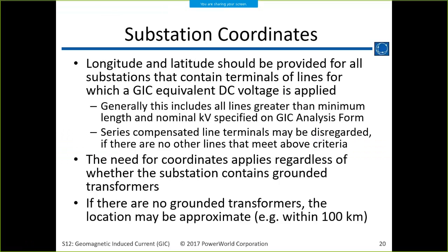So from your experience, on the lower kV 115, 161 kV systems, the lines are much shorter compared to the longer transmission lines, the transformers are scattered everywhere, and there's a lot of impedance on the system. For the same 5 volts or 10 volts per mile kind of default number, will including all that information actually change the results? Well, certainly having a shorter line is going to attenuate, but it's still a network, and it's still a source for GIC. I think it's also significant from the standpoint that at a lot of those levels you don't have VAR resources from generators to help offset the megavar.